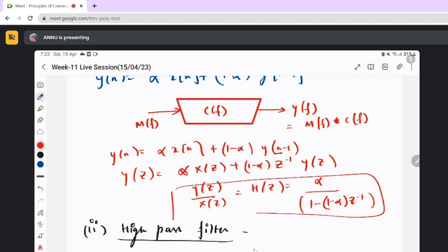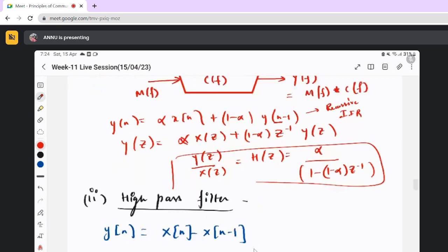So you are making it recursive with some phase shift and adding it back to have a feedback system. IIR, infinite impulse response, filters are recursive. They have y terms corresponding to feedback. Recursive systems always have feedback loops. You are taking the previous sample and using it for future prediction, using n minus 1. Causal. So this is frequency shift, phase shift.